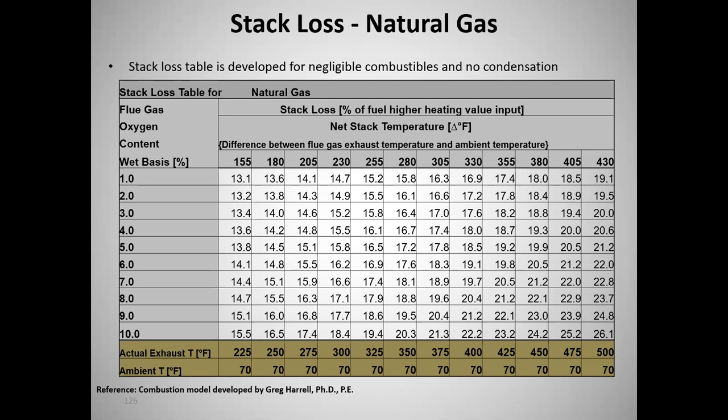But some more sophisticated, high-cost instruments want you to dry that flue gas, want you to condense out that water vapor before you put it in the instrument. And so those instruments would measure on a dry basis. And so you're going to get a different number because this is a volume measurement, or you can think about it as a particle count. Well, if I take all the water vapor out, I have fewer particles.